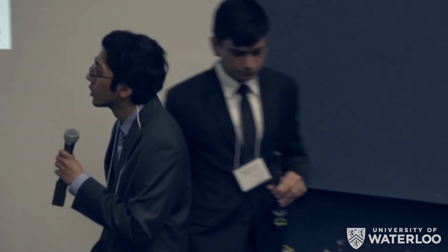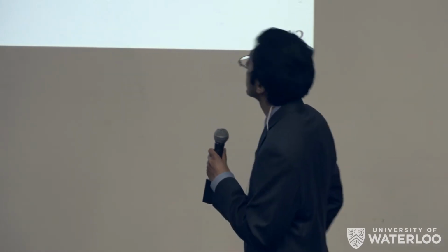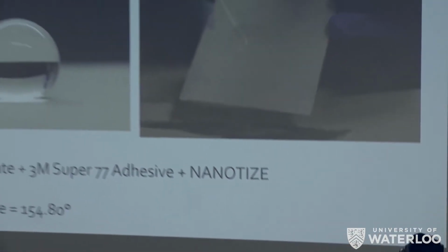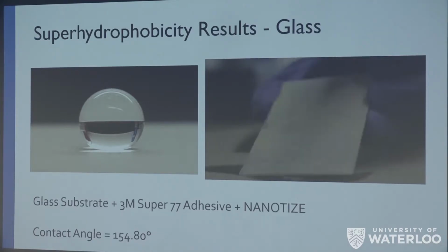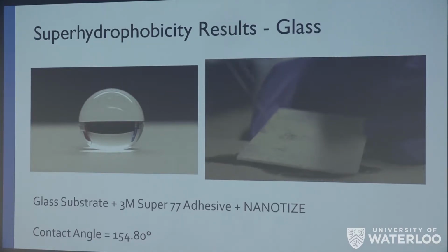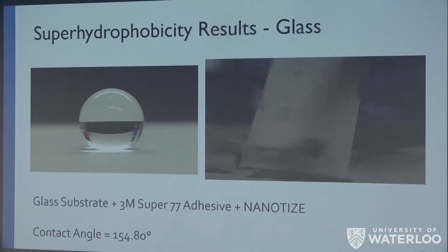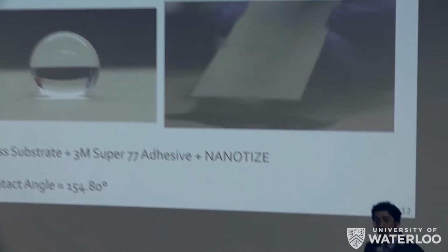So we applied our coating to a wide array of substrates. As you can see here, we have successfully transformed glass into a superhydrophobic surface. The contact angle is now greater than 150 degrees. Also, if you continue to watch the animation on the right, you'll notice that it's able to withstand a vigorous scratch test. After this scratch test, it remains non-wetting, and we don't see any leaching from the coating itself. Furthermore, I just want to point out that this coating was applied using the spray method. It dried within a matter of minutes. However, the coating is durable and it lasts for months.